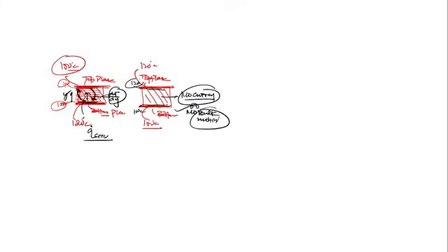In this case the heat transfer from high temperature to low temperature is via, tell me, purely conduction only. Yes or no? So even though this is a fluid, the heat transfer is through pure conduction. Clear, beta? Means anyhow, if we are able to cut the bulk motion in the fluid, that heat transfer in the fluid is via conduction.